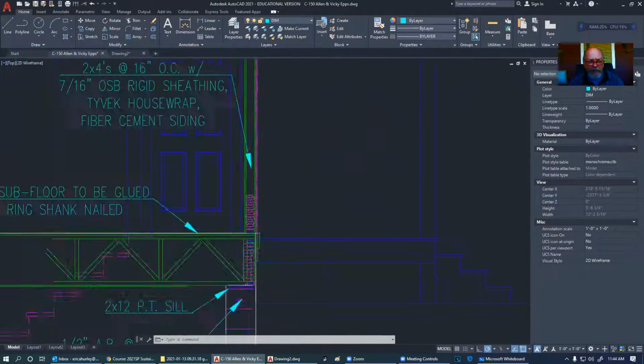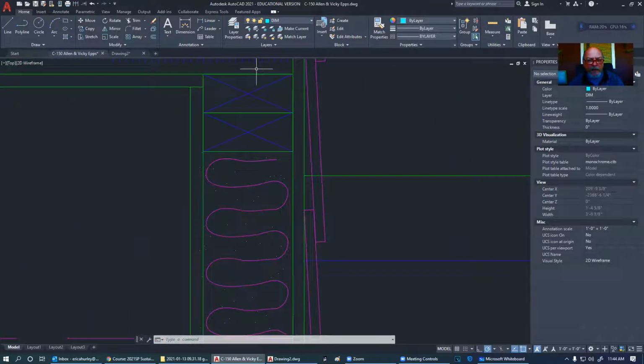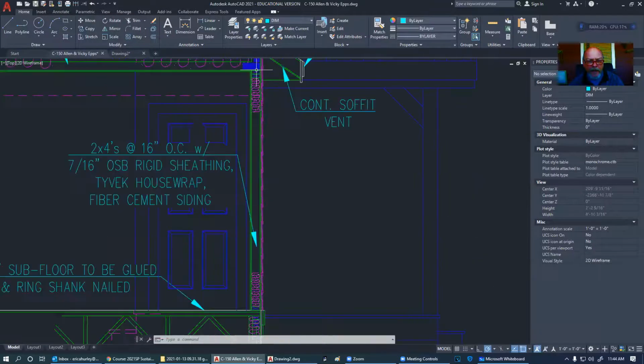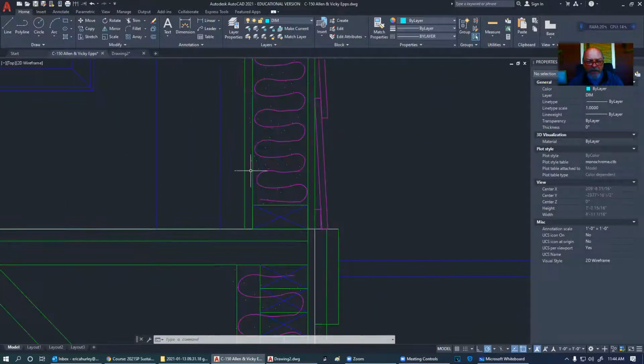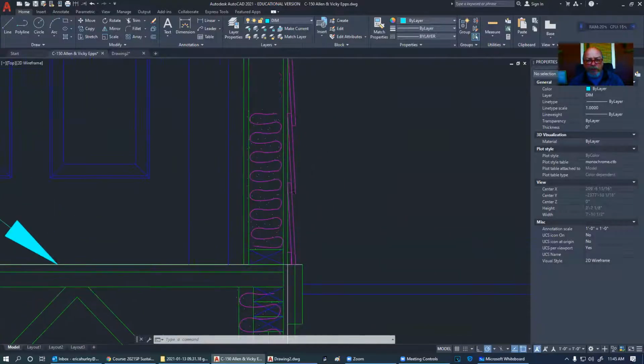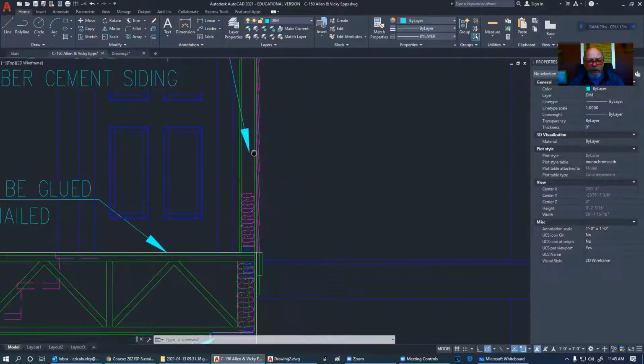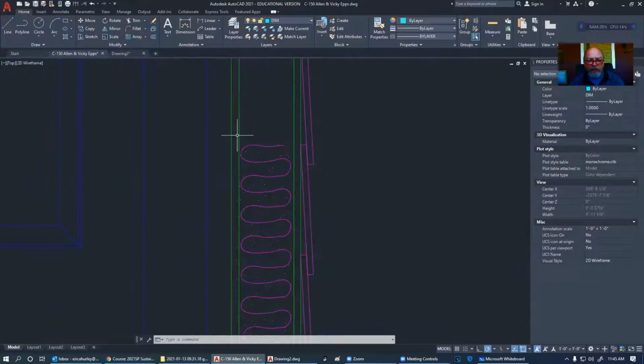So this is a typical stud wall where we have a double top plate. We have a single bottom plate. We have 1/2 inch drywall on the inside. And in this particular case, there's 7/16 OSB sheathing on the outside, and then we have a lap siding there. So I want you to draw, either on CAD or Sketch, a wall with its thicknesses.